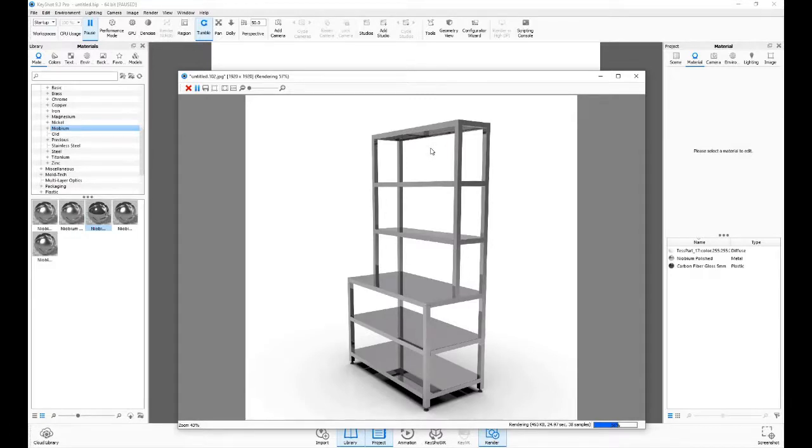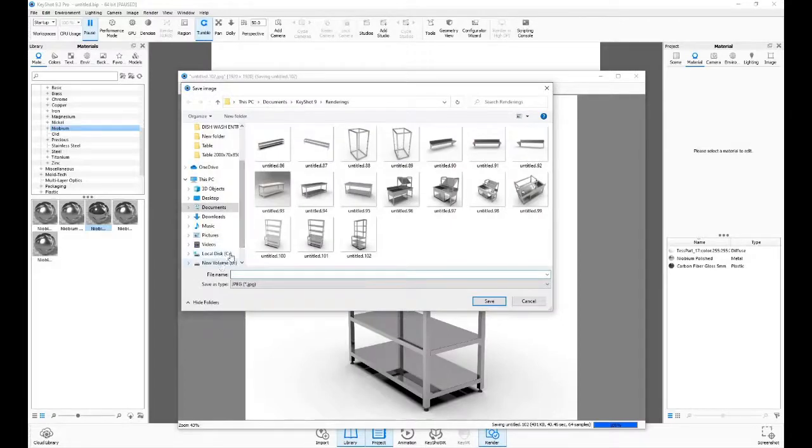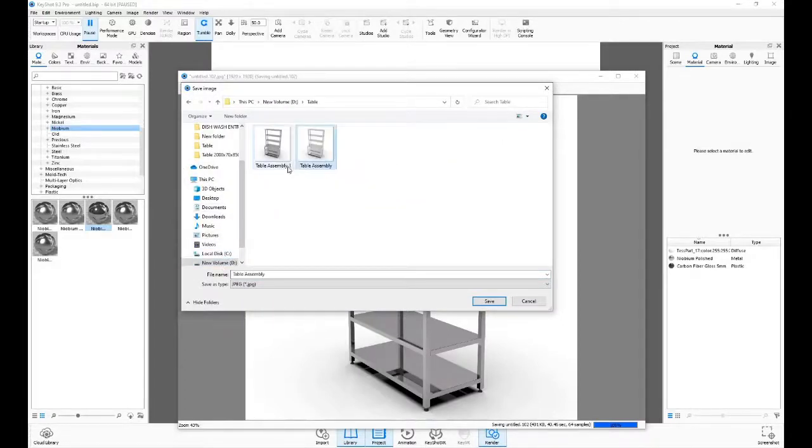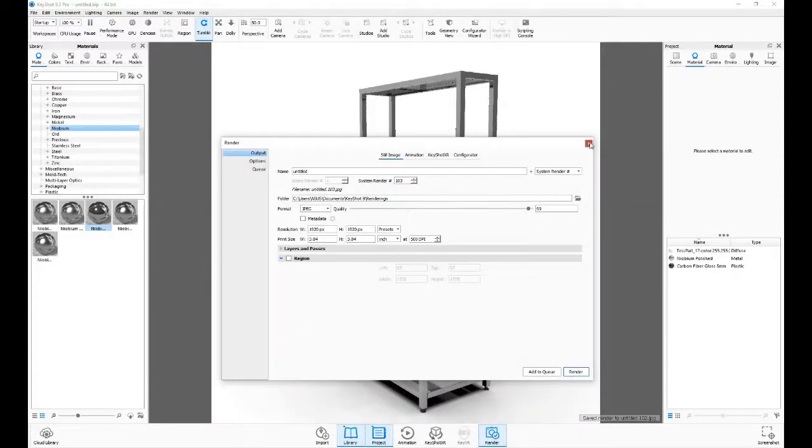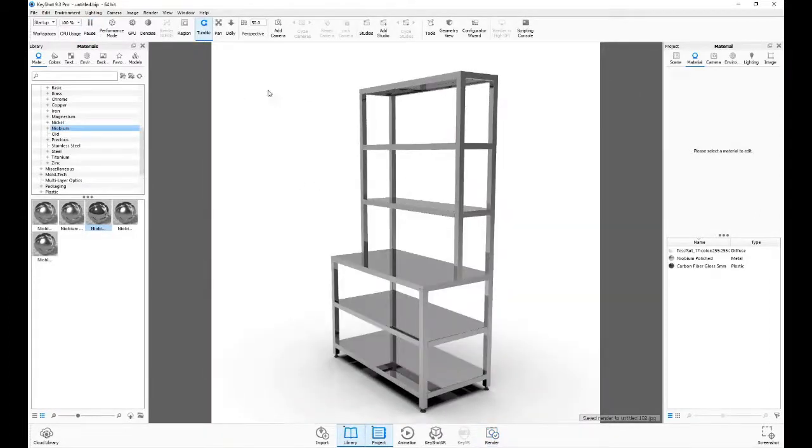We'll go back, uncheck, go into custom properties. We'll start off with the project and just double click that. And of course the project, we're linking it to the project number. So we'll go ahead and say OK. Safe working load, double click on that. Input, safe working load, and hit OK. So then I'll go back to previous. And now for the fun part of setting up some of the dimensions. So we'll select on that, hit next. And we'll start off with leg height. Again, just double click. For the inputs, we'll just say opening height. So when I change the opening height variable,